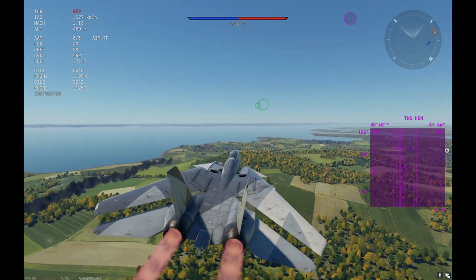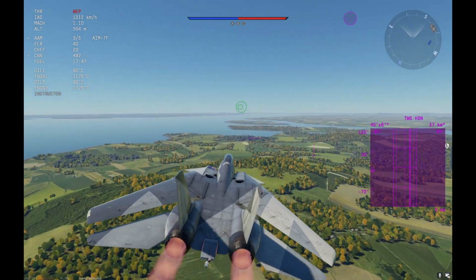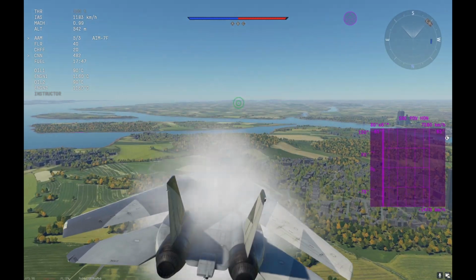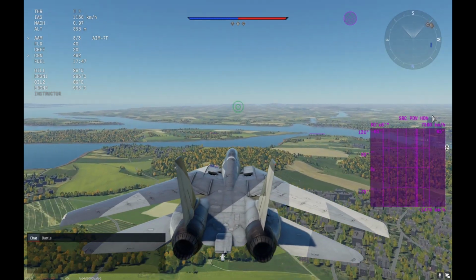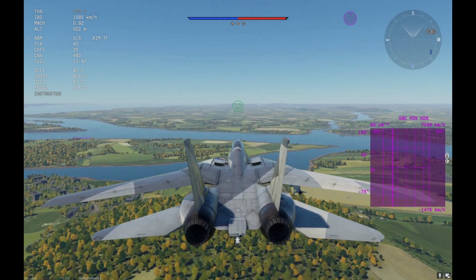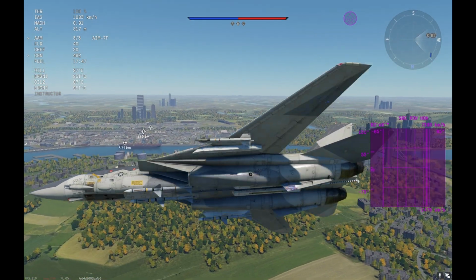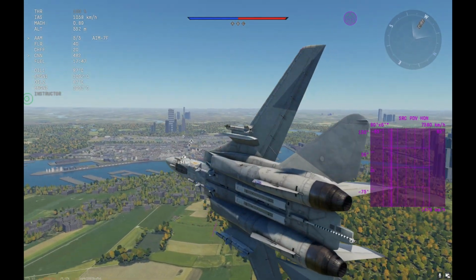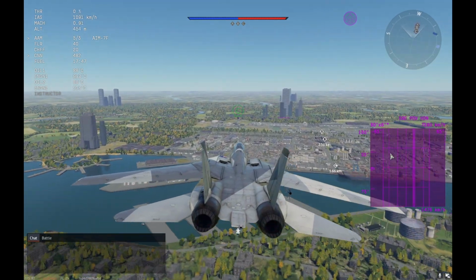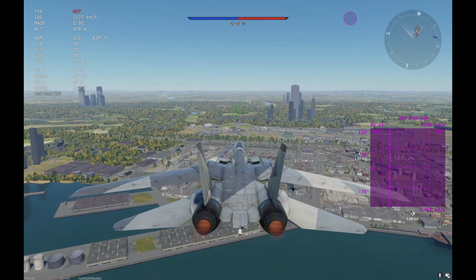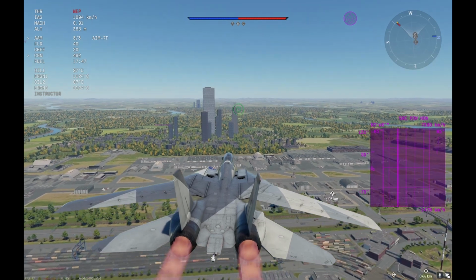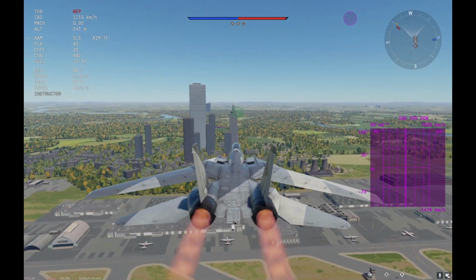Now pressing change radar / IRST mode button again, search pulse Doppler velocity head-on mode. Just reading that bit there. You'll notice 7,380 kilometers per hour isn't really a distance. It's not a distance. What this radar here means, the further up it is, the faster you're approaching the enemy. So this is about relative speed to a target.